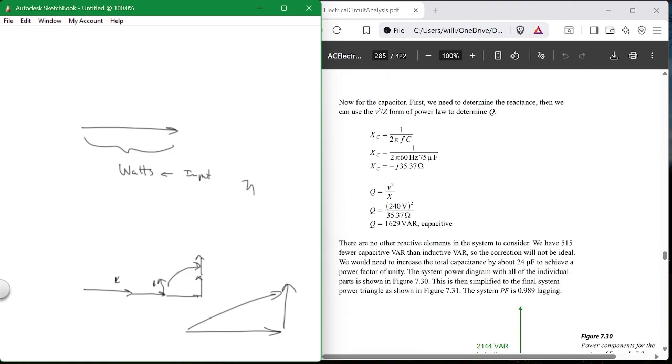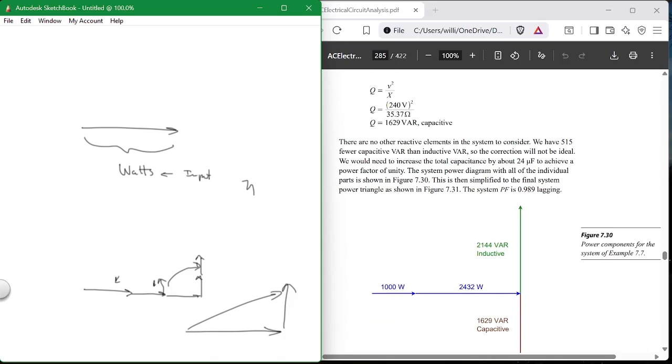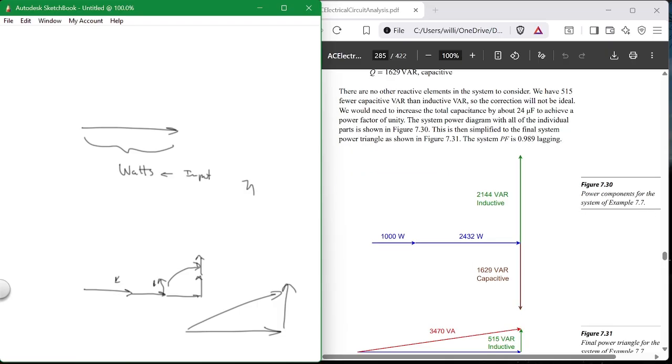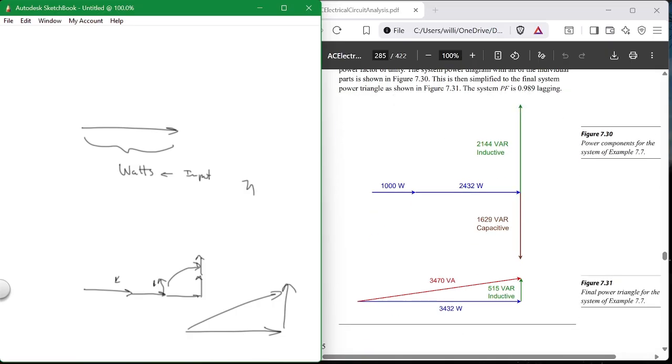Okay. So here they are. Here's your first one, and here's your second one, and that's the total. And now if you had a capacitive load, if you had some capacitors, there they are, and they're your final answer. So he's adding capacitance to the reactance to bring this down to something that's a little bit nicer. As long as you get close, you don't have to. What's the cosine of this angle? 0.999 or 0.990 or 0.980 or whatever. You're within a percent or two.